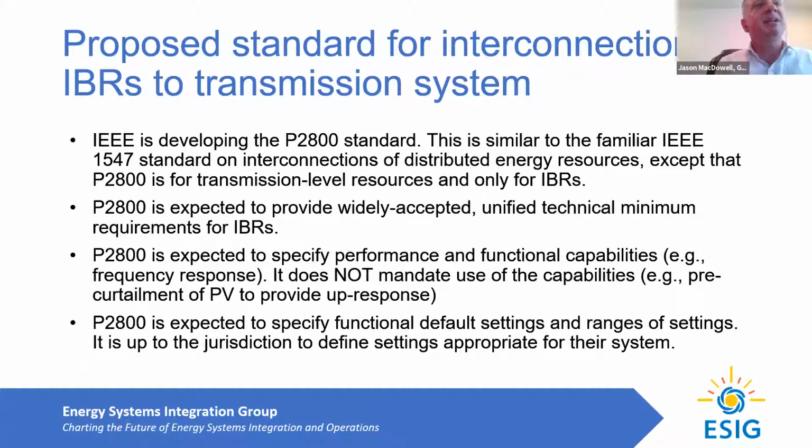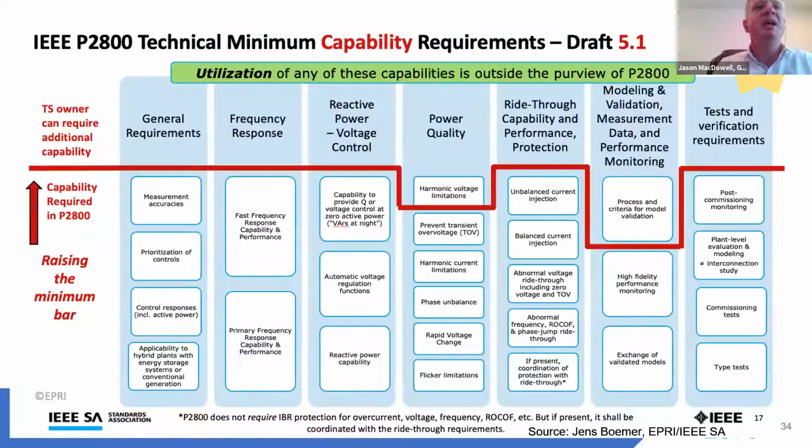It's a matter of adopting the standard in all of the jurisdictions and the regions in order to deploy the capability, at a minimum, to enable the capability and the features of inverter-based resources to support the grid. So as I said, this standard covers frequency response. It covers reactive power control, both in terms of reactive power injection and also for batteries, reactive power absorption